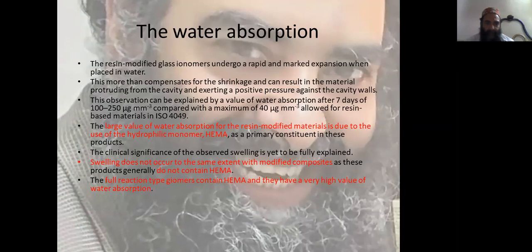This observation can be explained by a value of water absorption after 7 days of 100 to 125 micrograms per cubic millimeter, compared with the maximum of 40 micrograms per cubic millimeter allowed for resin based material in ISO 4049.